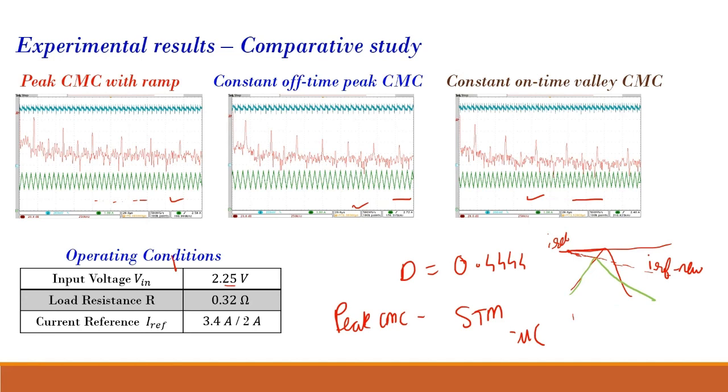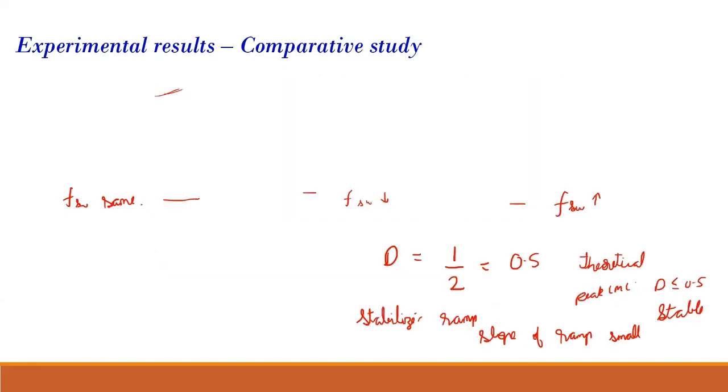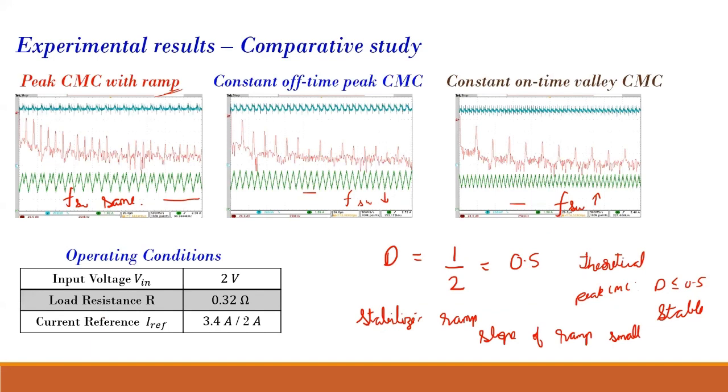Is this ramp compensation the same as the emulated ramp concept, or is it different? No, this is different. Emulated ramp is internal, inside the FPGA. That is for fully digital current mode control. Okay, I thought both were the same. No, they are not.